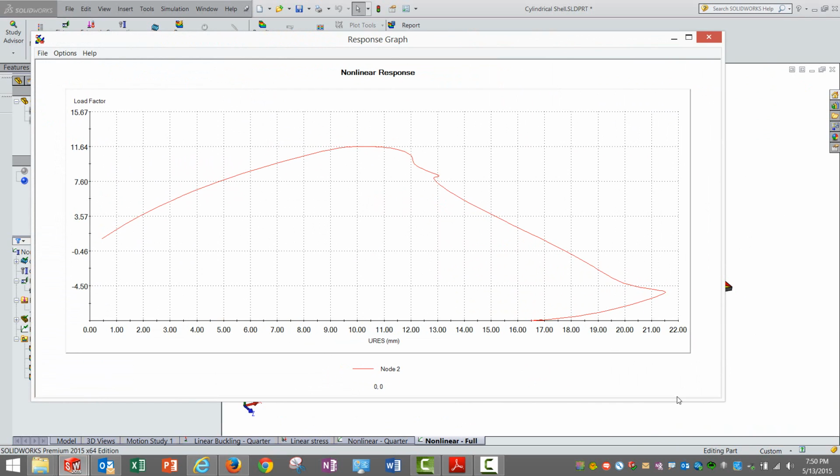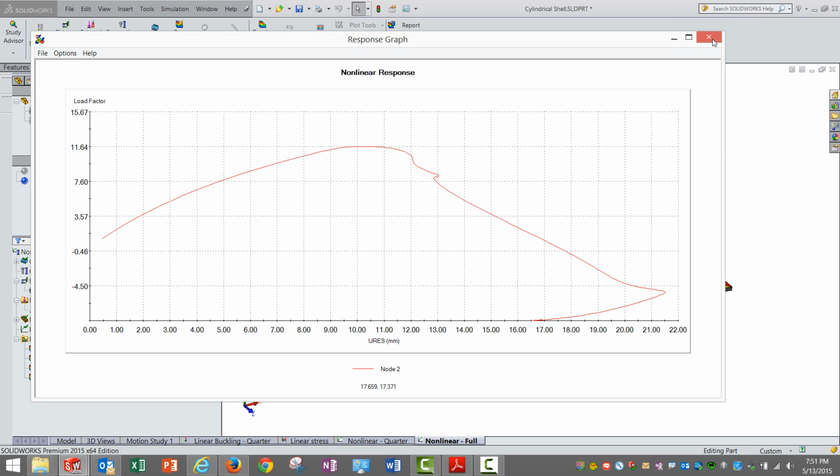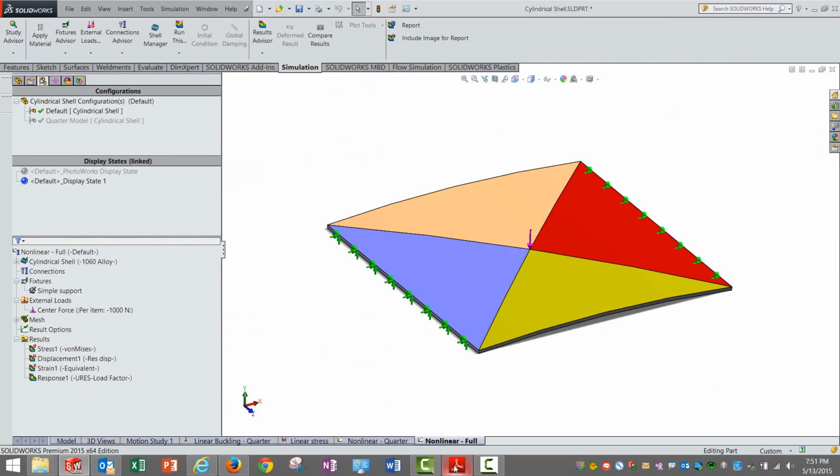So this is what I'm saying. Number one, this can be captured only with that small split surface or loading change. The location of force has led to a thought that symmetry is not present in the model, so obviously we need to take the complete model, and thereon the post buckling behavior is very different, and that's what you can observe down here. Rather, the buckling values over here have dropped further, and it has gone below 13, somewhere around 11 we can consider. So obviously it is different from the 13 we saw in the nonlinear buckling with symmetric conditions.